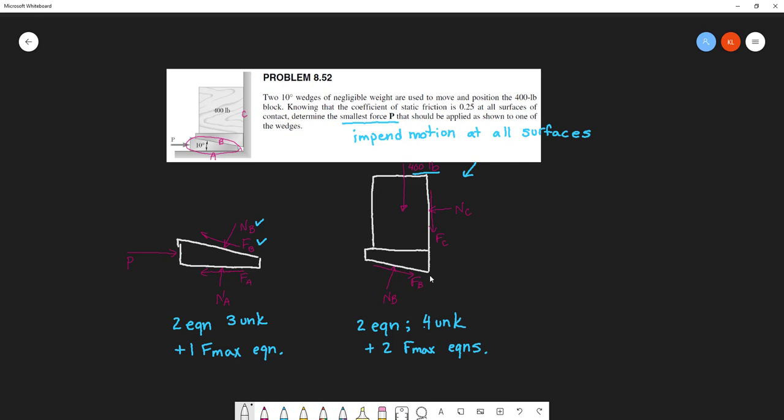We are missing a few things in our free body diagrams. Given the number of forces and the directions, we're going to stick with just an x and a y axis, which means I need to know some of the angles down here. So the friction is along that 10-degree angle, and the normal force is perpendicular to that. So its 10 degrees goes to the vertical, not to the horizontal. All right. FBD2.